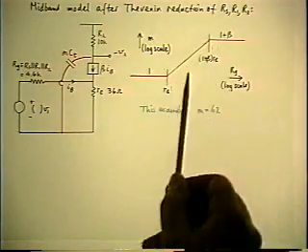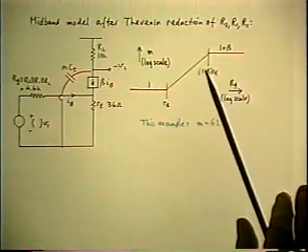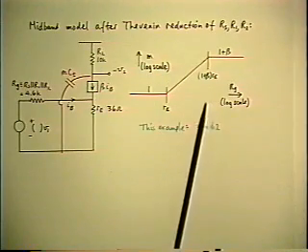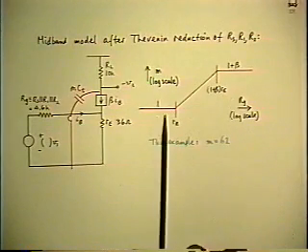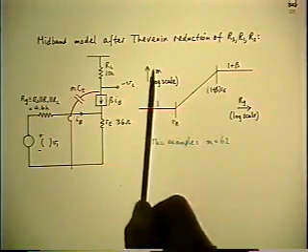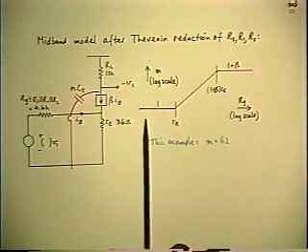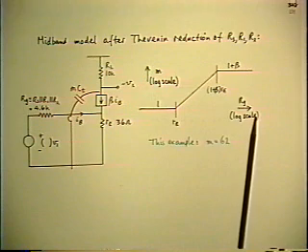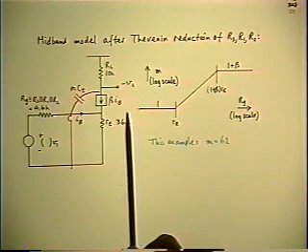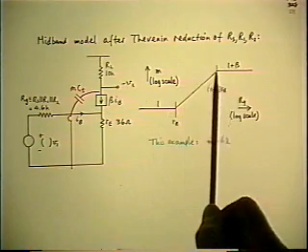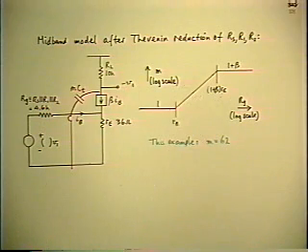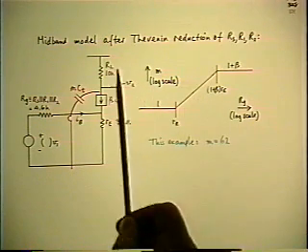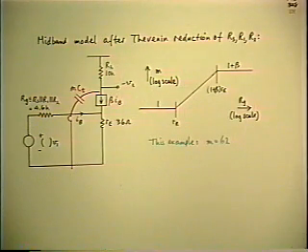And here's the graph of that function. It's also convenient to use a double log scale, so that the same geometry to do with asymptotes that we already know all about can apply to this case as well. So here I plotted the multiplier on a log scale versus RG, also on a log scale. This exposes the low RG asymptote of 1, the high RG asymptote of 1 plus beta, and in the intermediate range, a single slope, 1 for 1 again, or 20 dB for 20 dB, or 20 dB for an order of magnitude, however you want to interpret it.